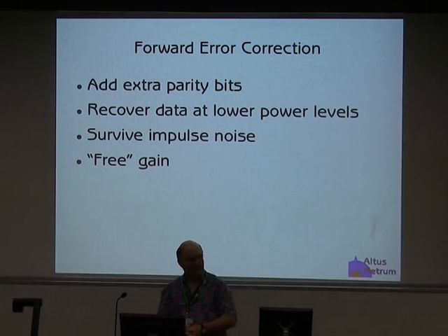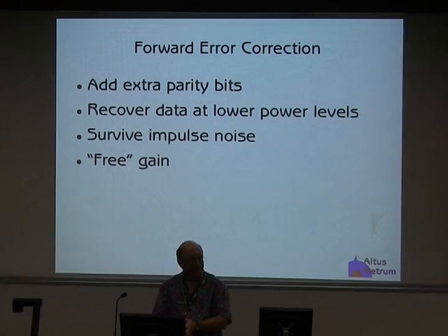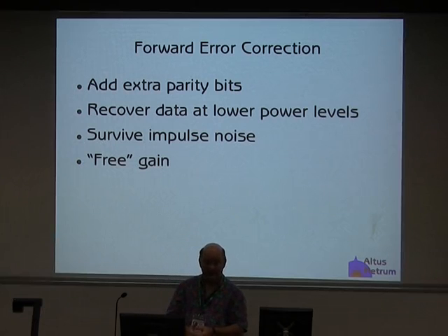I know there are a lot of people that have built digital radios that don't use forward error correction. They're insane. Don't listen to them. Just nod and say, "That's very nice, dear. I'm glad you have a radio." But anybody doing anything sensible in digital radio is going to use forward error correction because, again, it's free gain. It costs you $0. It costs you just a bit of software. And so all that forward error correction does, of course, is add extra bits to the data.